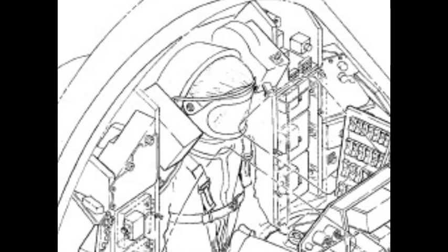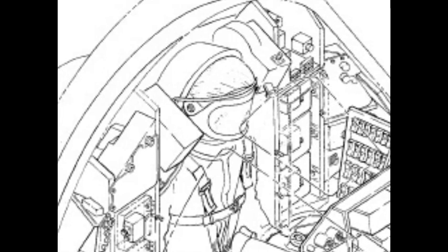4 titanium panels, butt-welded together, form the adapter skin. Vertical hat sections internally welded to the adapter skin provide structural reinforcement. A steel flanged ring is riveted to the bottom outer surface of the adapter. The ring flange is provided with holes to enable the attachment of the adapter to the missile with bolts. Riveted to the top outer surface of the adapter is an aluminum flanged ring.